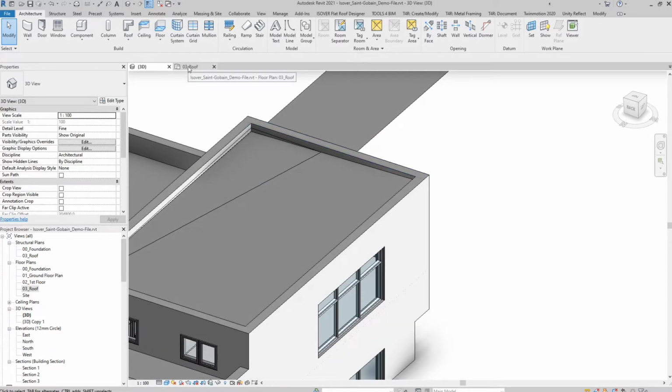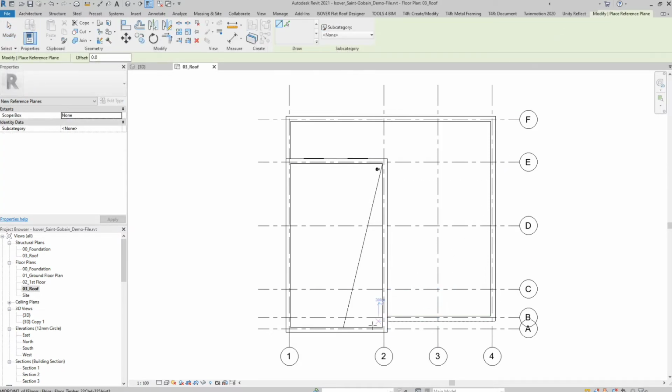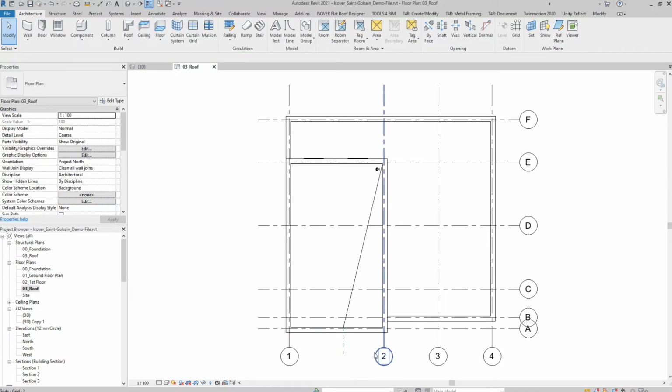Since we want to subdivide our roof surface for further roof adjustments, we will use a reference plane to position our point for that purpose. Draw a ref plane in the direction parallel to our wedge volume, starting from the diagonal edge end on the wider side of the wedge as shown in the video.